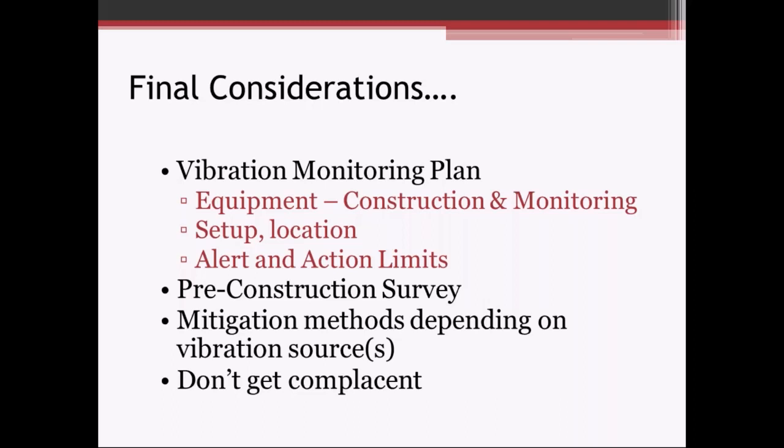Pre-construction survey, lots of value in the pre-construction survey, and even just with property owners knowing and seeing that there's somebody going around documenting the condition of their structure, they're going to think twice about calling and saying, hey, you cracked my foundation or something like that. They'll think, I wonder, maybe that crack was already there. 9 times out of 10, when people have called us up, we've been able to produce pictures from before any of the work started that identified some of the defects that they were claiming the contractors had done.